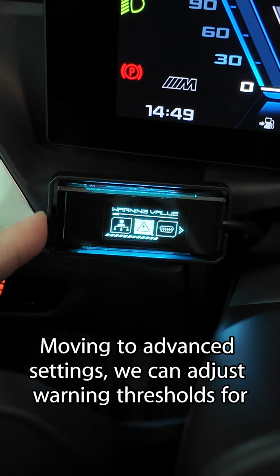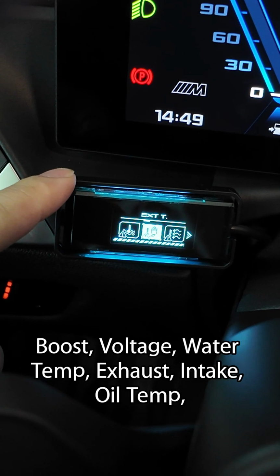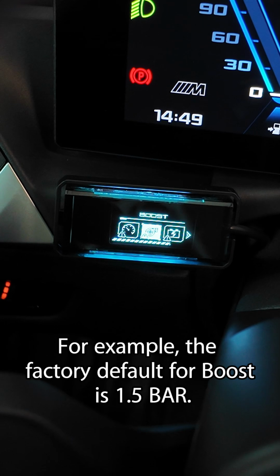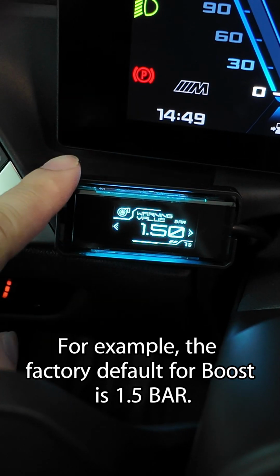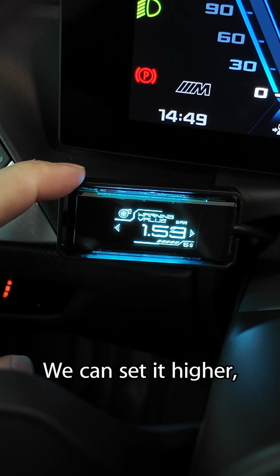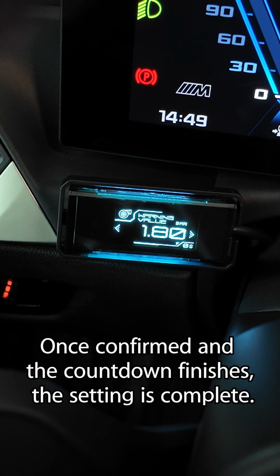Moving to advanced settings, we can adjust warning thresholds for boost, voltage, water temp, exhaust, intake, oil temp, transmission, RPM, and speed. For example, the factory default for boost is 1.5 bar. If a high-performance car exceeds this, the alarm will sound. We can set it higher, like 1.8 bars. Once confirmed and the countdown finishes, the setting is complete.